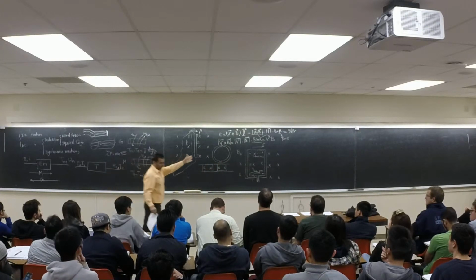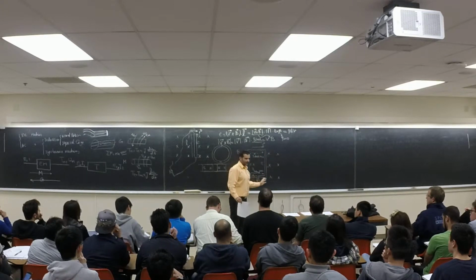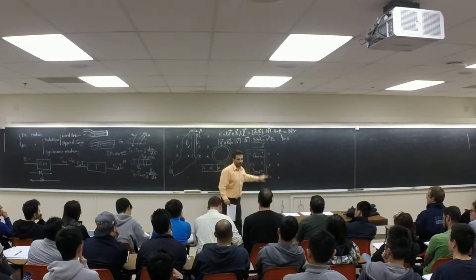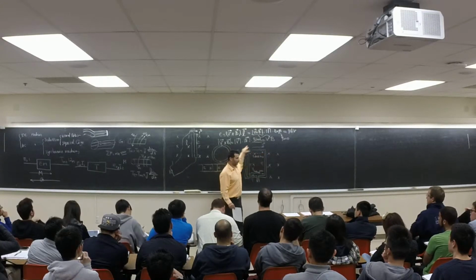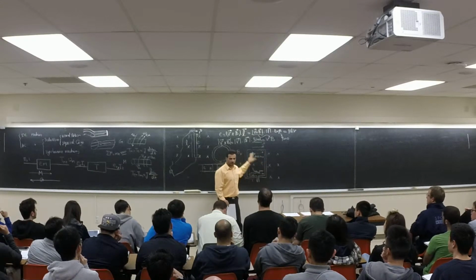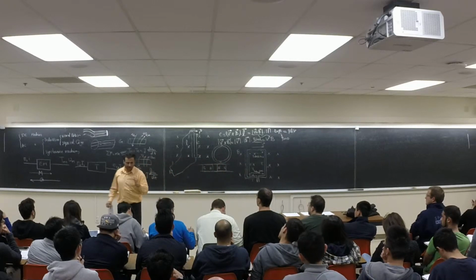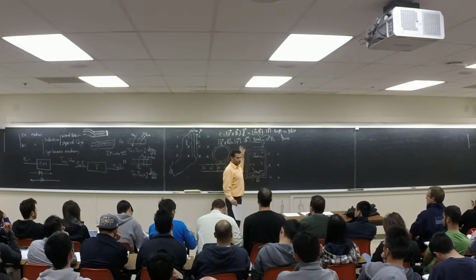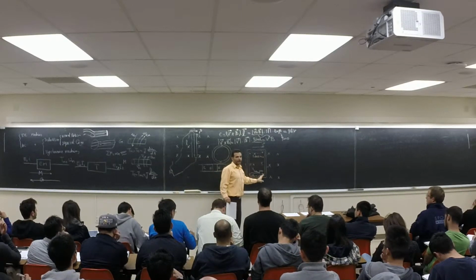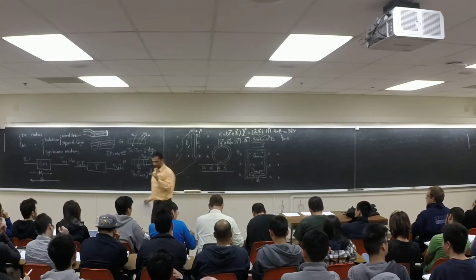So these two, they are important. These two legs. We call this one a turn, you can see, and each of these legs is called a conductor. One turn, and each of these is one conductor. Basically, one turn is two conductors. If you have n turns, think about it. Maybe this one was, I don't know, 20 turns, right? Overall, you are going to have 40 conductors, double the number of turns, right?